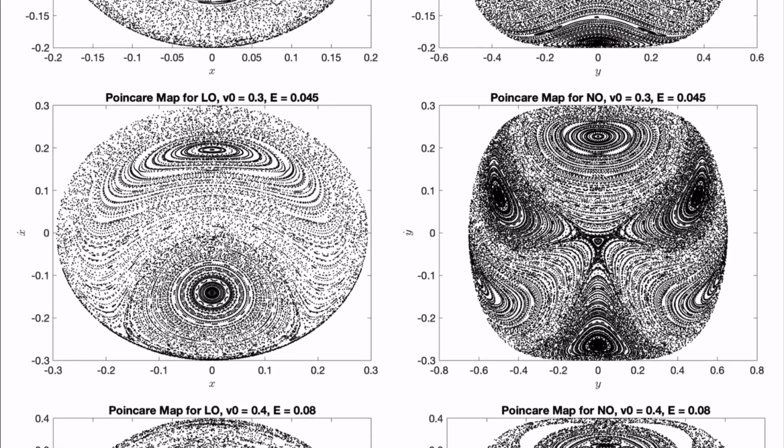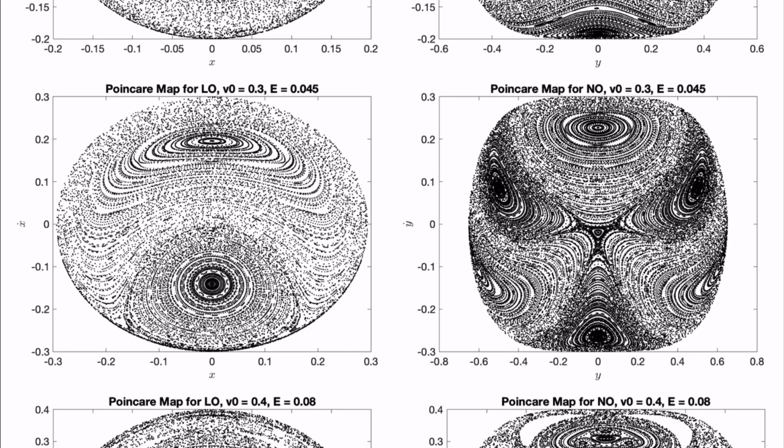If we go back up higher in energy, we now see that on the left plot there's an emergence of two fixed points, one that I'm just circling right now, and then another one up here. This is actually where the two NNMs begin to cross each other, and there's some intersection and conversion and so forth. If you take a look at the right plot, you can see that there's a single fixed NNM in the center, and it is potentially surrounded by some unstable fixed points.